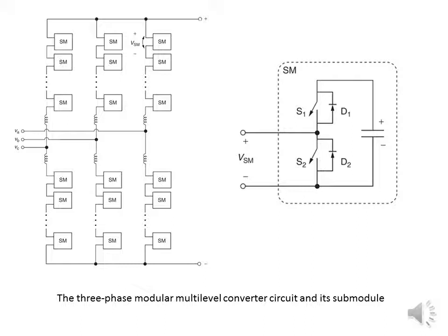The modular multi-level converter is actually a cascaded half-bridge multi-level inverter. It's a single DC source configuration. Each submodule contains a half-bridge inverter with a dedicated DC source, in this case a capacitor. Using a sequential switching strategy, the capacitors are charged using the common positive and negative DC buses and are switched to produce the step output waveform that approximates the desired sinusoidal waveform. However, the capacitors could also be replaced with independent DC cells in each module.